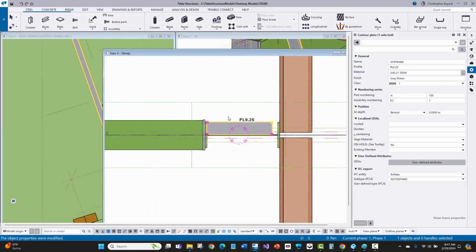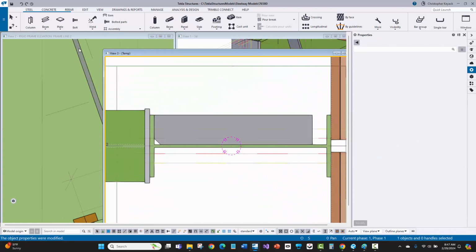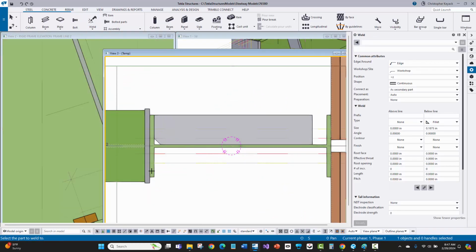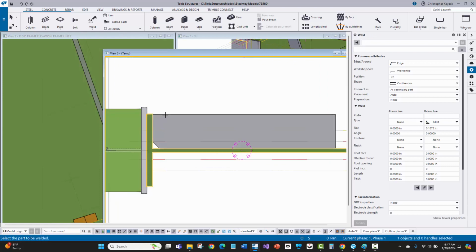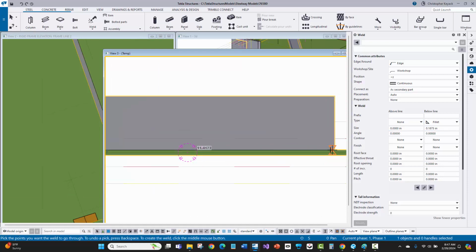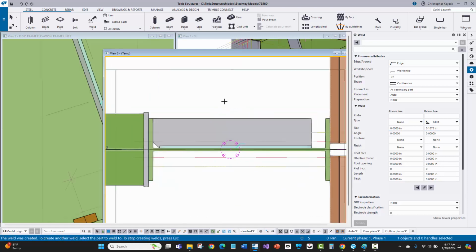All right, now what I'm going to do is I'm going to do a polygon weld. So we'll come up here to weld, and we'll say create polygon weld, and I'm going to weld that between this part and then that plate. And I can pick my 2 points, but let's just look at the size here. It looks like near side wants a 3/16, and then for this one, see, so the main part looks like on the web we only need it on one side, so I'll pick 2 points.